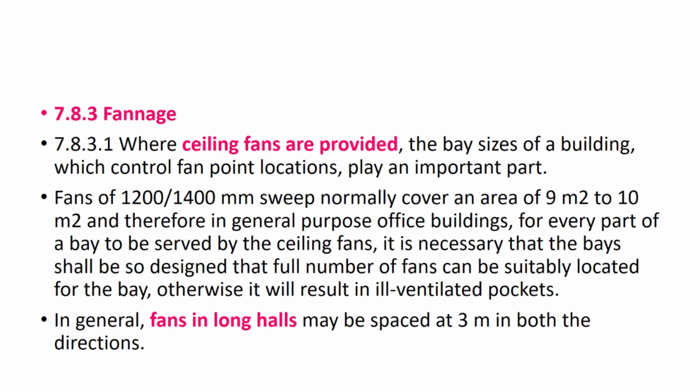So what you are supposed to do is that, suppose it is at a greater depth, then whatever the width of the fill is there, it should be more than the width of the foundation. Suppose the width of foundation is 2 meters. With a dispersion rate of 2 vertical to 1 horizontal, suppose it comes to 4 meters at that particular depth.